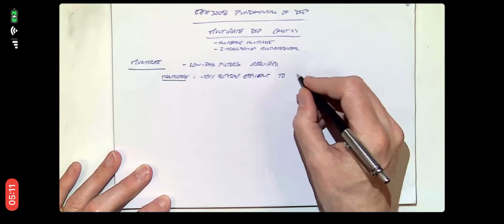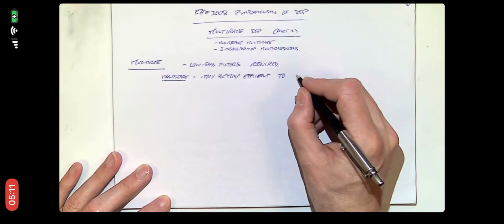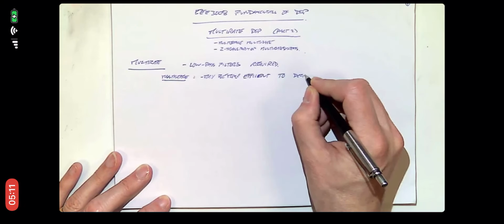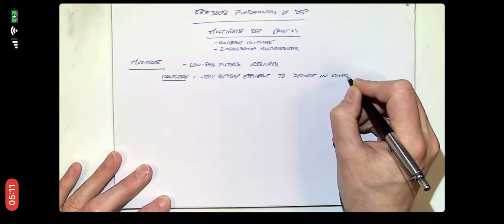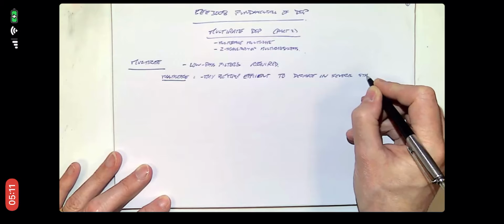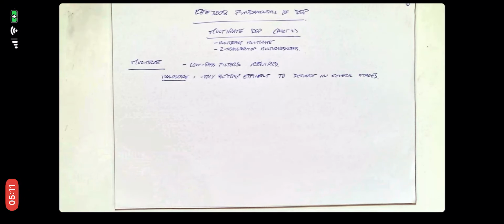to, let's say that we want to decimate in several stages. So far what we talked about was using a single filter to create a low-pass filter for decimation, which we then reduce the sampling rate all in one go.